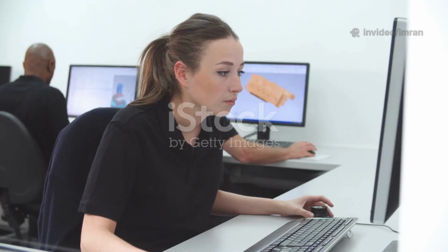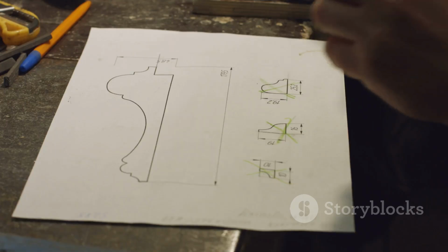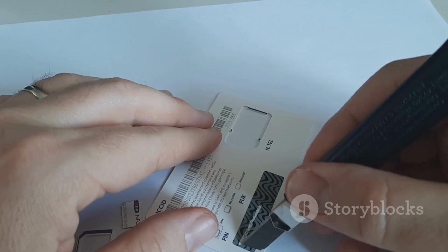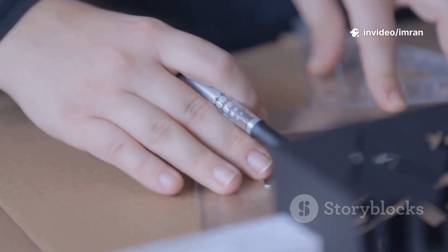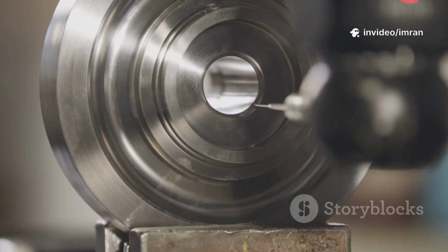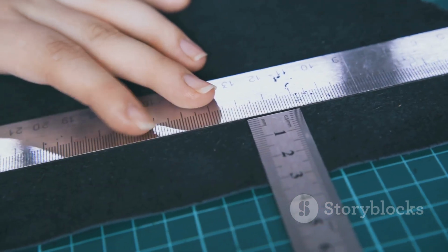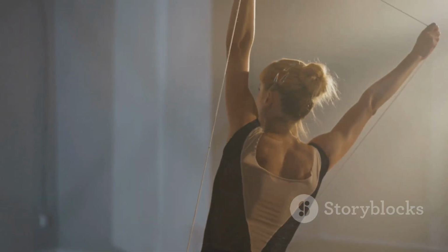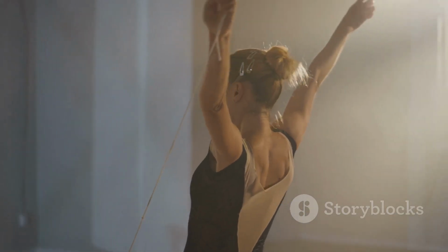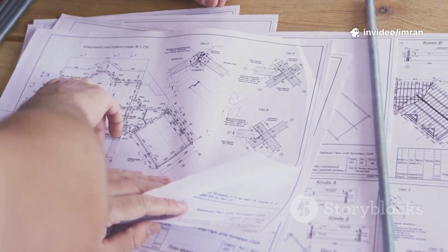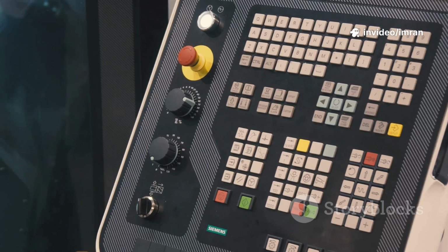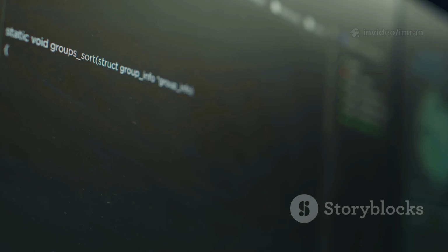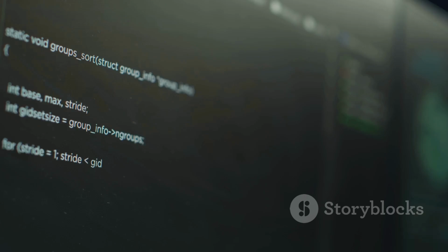The Extend command is the perfect companion to the Trim command. It's essentially its direct opposite. While Trim is used to shorten objects, Extend is used to lengthen objects until they meet another object. This is extremely useful when you have a line or an arc that falls just short of a boundary and you need to close the gap precisely. The Extend command saves you from manually stretching the object and trying to make it meet the boundary perfectly. You can find the Extend icon in the flyout menu under the Trim icon in the Modify panel. The command alias for Extend is X.